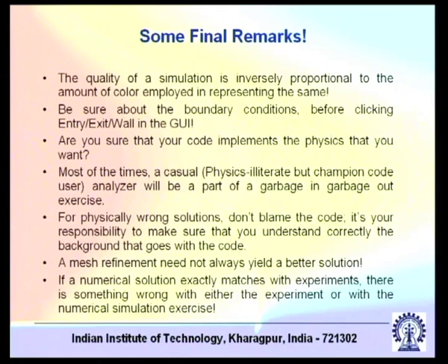If you are solving for theta as a variable and then implementing the outflow boundary condition, fine, but not if T is the variable. So you have to be very, very careful whether the boundary condition that you are implementing is representing the right physics. Not only the boundary condition, in general, are you sure that your code implements the physics that you want? This is very, very important because all problems do not have the same physics. Say you are interested in solving a rarefied gas dynamics problem. In that case continuum equations may not be valid, and maybe you may require molecular simulation or mesoscopic simulation; several other types of simulations are there.